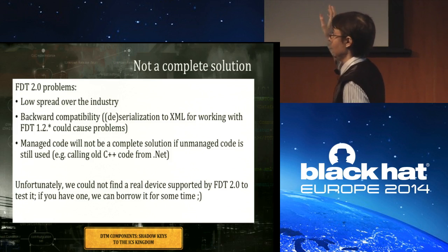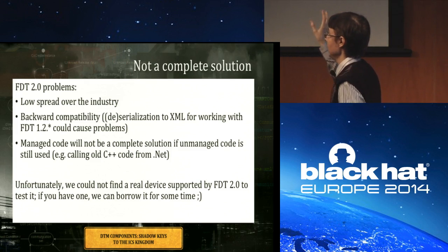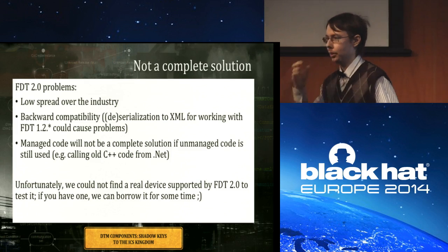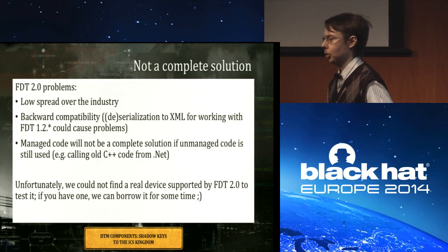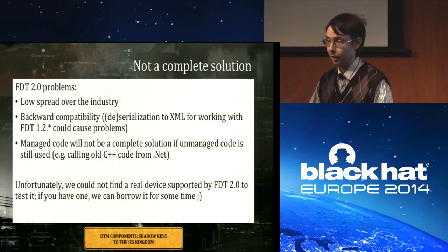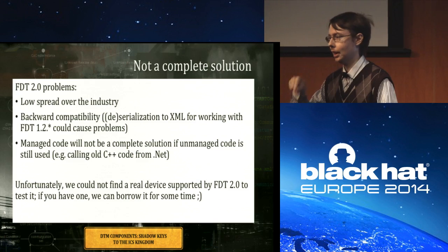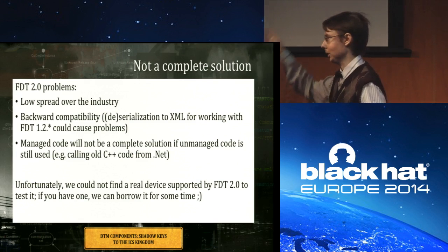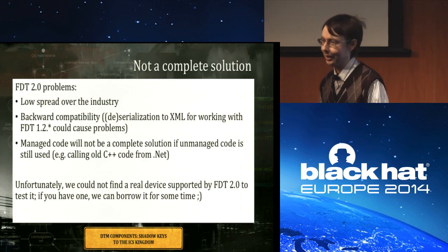Also, managed code is a great idea, but it will not be a complete solution if unmanaged code is still used. For example, we've seen some DTM components with a really, really secure front end on .NET or Visual Basic, but inside it calls unmanaged C++ code with such memcpy_s or other funny things.